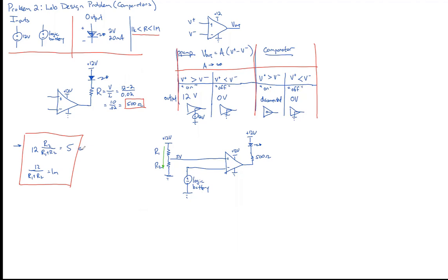If we made this part down here equal to 12, then that 12 and this 12 would cancel, and we just have R2 equals 5. In other words, if we just had R1 plus R2 equaling 12, then we know R2 would have to equal 5 to make this work. And then from the top equation, we know R1 would have to be equal to 7.